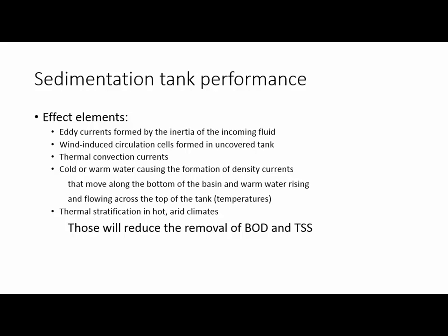There are some elements which affect the performance of the sedimentation tank. The first one is the eddy current formed by the inertia of the incoming fluid, and the second one is the wind-induced circulation cells formed in the uncovered tank. The third one is thermal current.